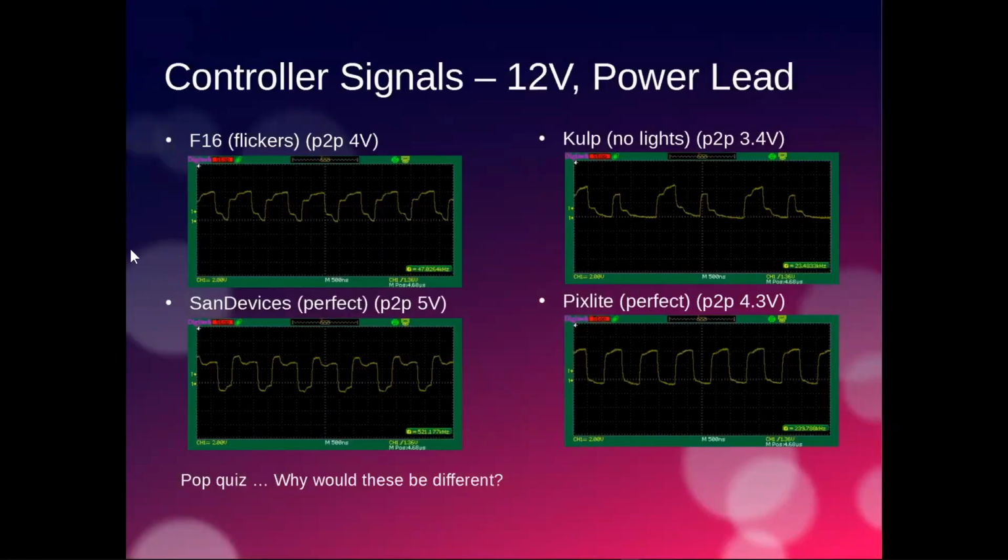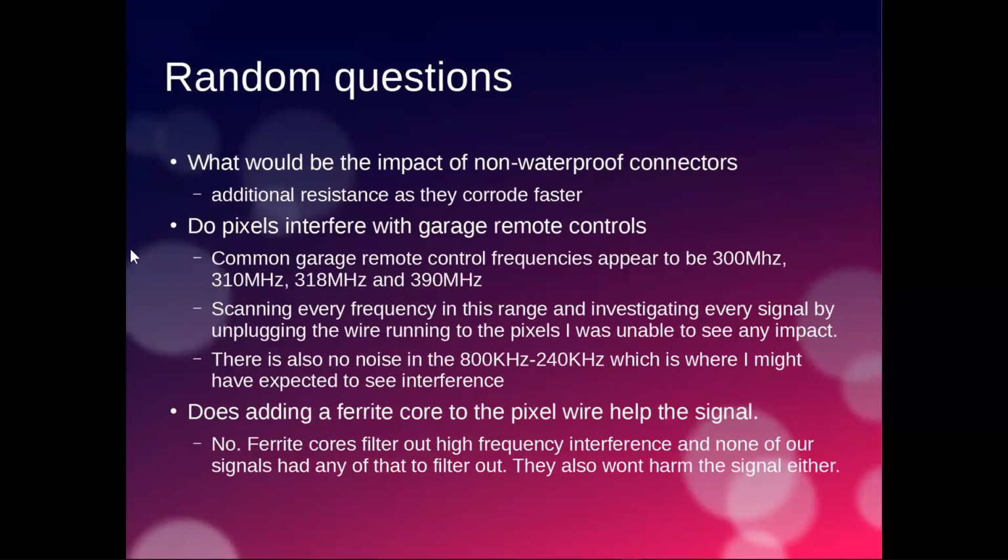All right. So while I was doing this, I also had some other random questions, and I got a variety of answers, or non-answers, to these. What happens if you use shoddy connectors? The only thing about shoddy connectors is that they will obviously introduce additional resistance, which means that the voltage lift on your ground wire or the drop on your data wire will be slightly higher because you're using non-waterproof or waterproof connectors that have degraded. So you do want to keep your connectors reasonably good, particularly if you're trying to get distance out of them, because otherwise the problems that you experience here will be even greater.